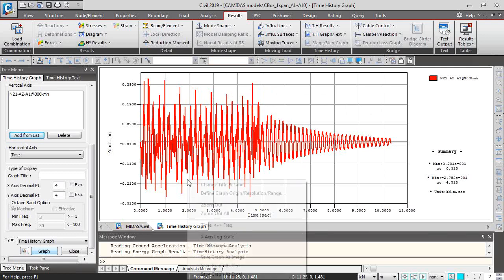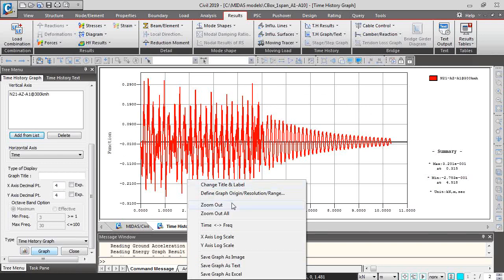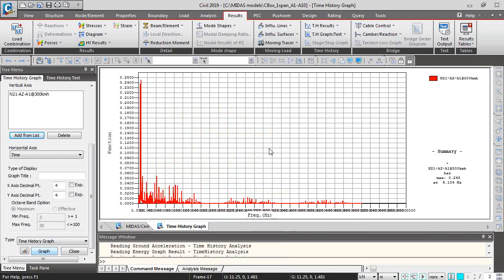Right, you can plot that as frequencies as well. And that will help you to understand which frequencies are more excited and if that makes sense to you. Usually, the lowest frequencies mean you need less energy to excite the motion of your bridge, so usually they are the ones that have greater contributions.